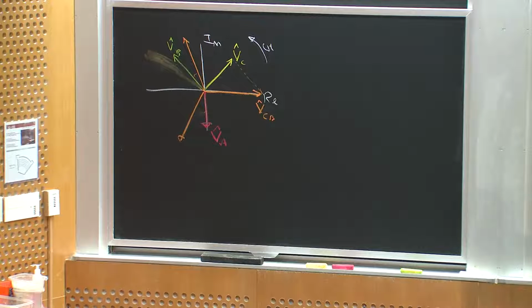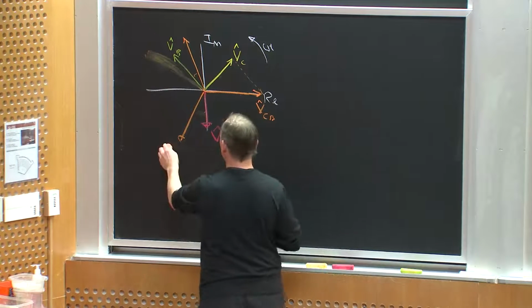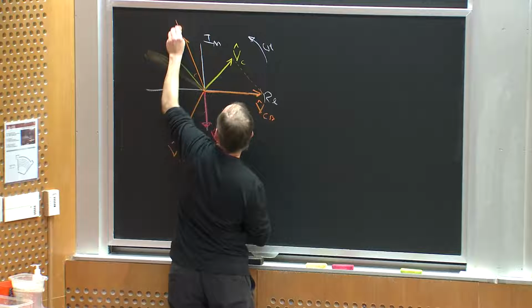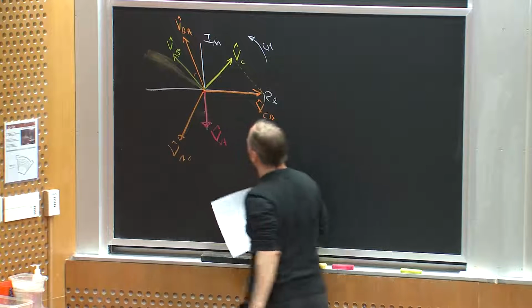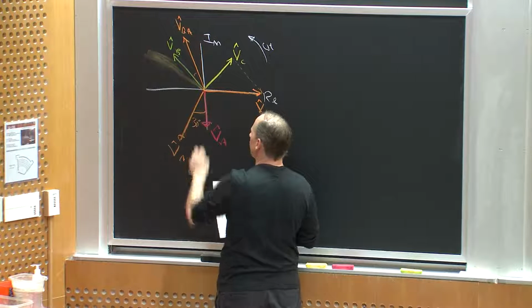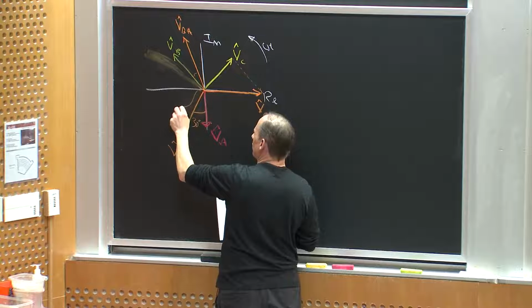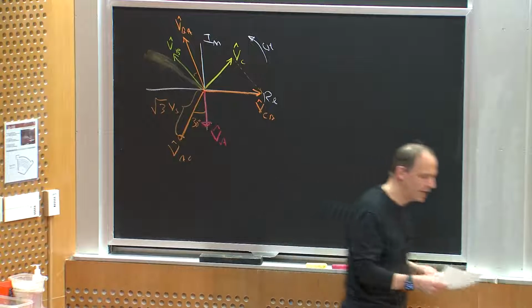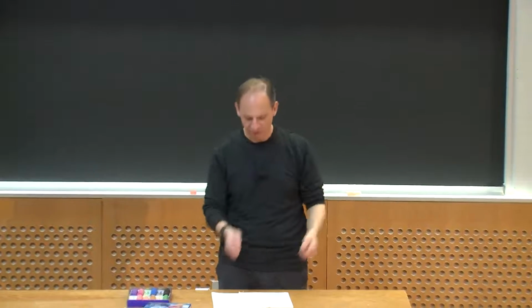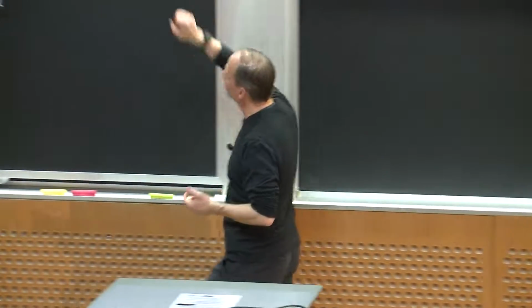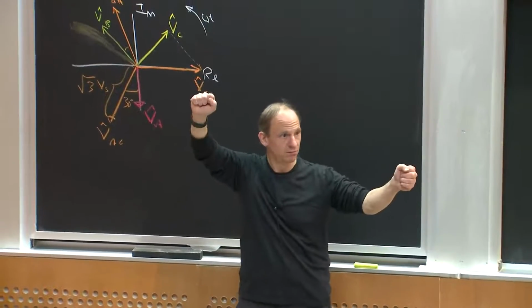VCB is going to be a cosine, VAC hat is going to be phase shifted here, and VBA hat is going to be phase shifted here. So what I end up with is a 30-degree phase shift, and the length of these phasors is going to be the square root of 3 times Vs. So the line-to-line voltages are square root of 3 larger than the line-to-neutral voltages, and they are phase shifted by 30 degrees. And in fact, how do we get these? We're essentially taking differences of two voltages.